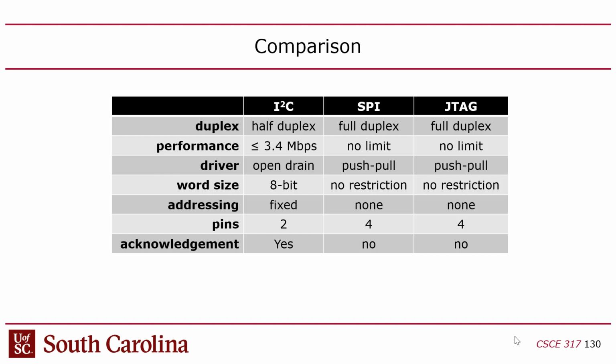So they programmed that, they calibrated that to go into a busy loop for a calibrated number of iterations to match the amount of microseconds you want to sleep. So it doesn't use any kind of external timer or external clock at all. It's just a loop. The problem with using the sleep function is that